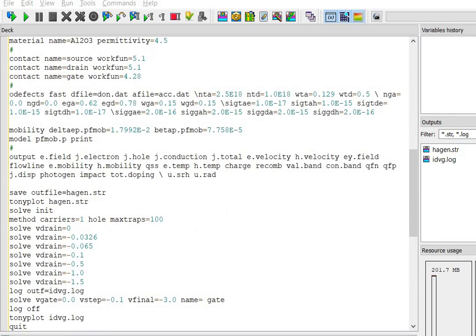One more thing I have missed out is organic defects. If you specify the parameter dopant on the organic defect statement, then the trap density defined using NA, sigma A, EA, ND, sigma D and ED parameters will be used in the dopant singlet excitation calculation. Organic defects activate the band gap defect model for organic polymer materials and set the parameter values. This model can be used when simulating organic polymer devices using the organic display and organic solar modules.